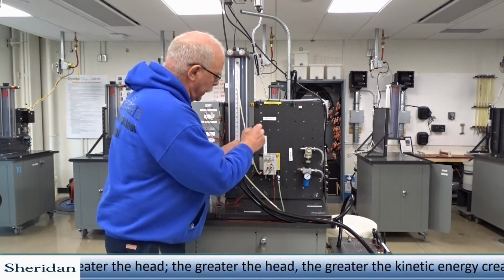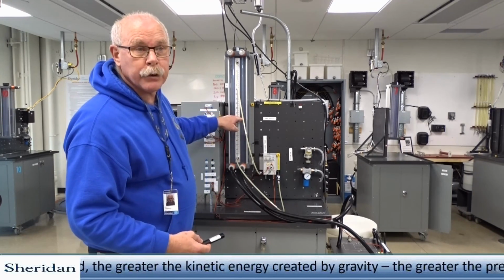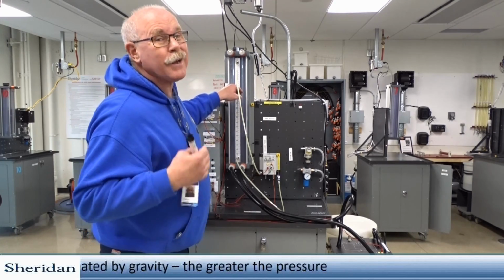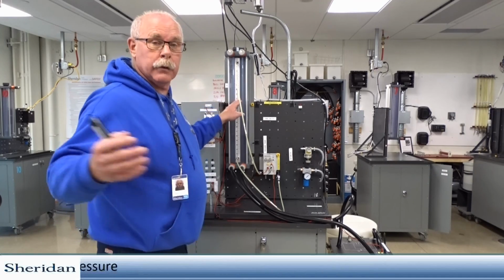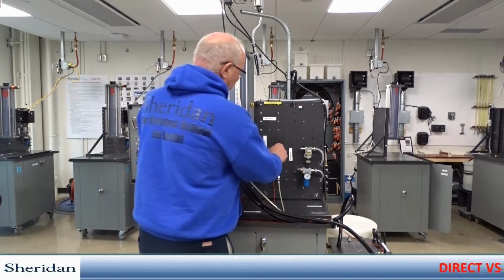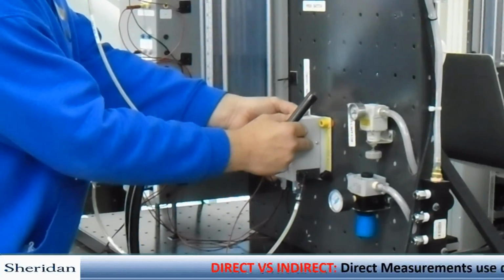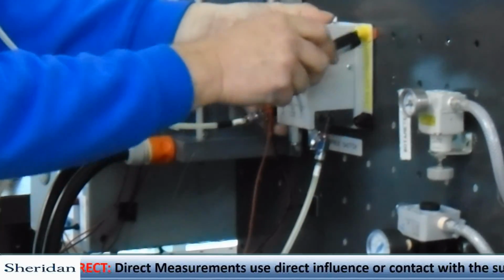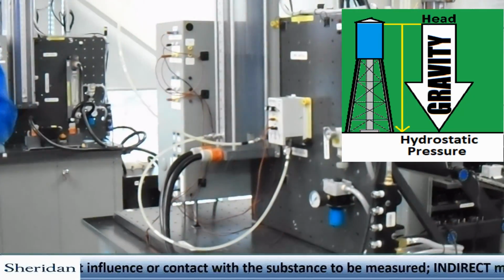By dropping it down, I had greater head of water above the transmitter. It was reading a greater pressure, thinking that the water level was higher than it actually was. Once I move it down, the control goes, hey, the water level's too high, I've got to bring it down. I'm going to move the transmitter back to where it was, and in fact, by doing so, I'm reducing the amount of pressure that's coming into the transmitter. And now it's back to originally where it was.